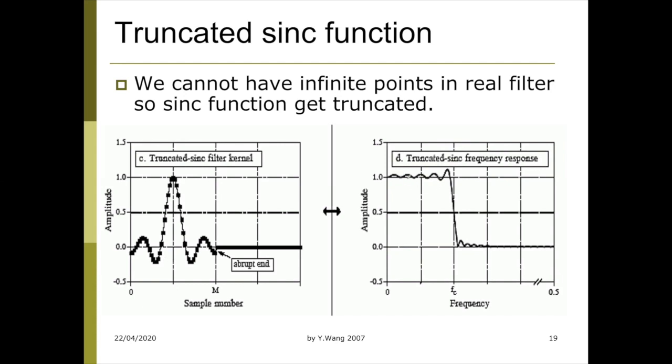It will still perform as a low pass filter in this case. But in this case, the low pass filter is going to be non-ideal. It introduces the pass band ripple, the stop band ripple and the transition band. So really it's trial and error. We basically take a certain part of that and then we end up with a certain non-ideal filter.